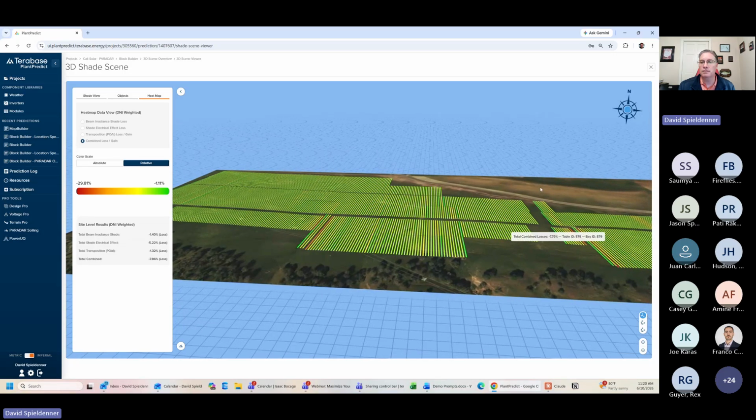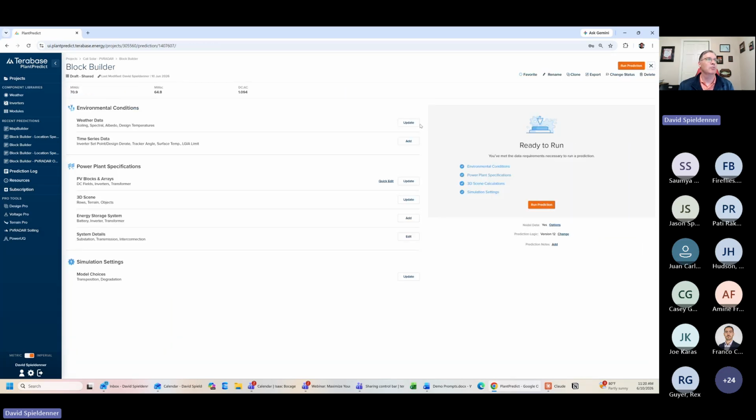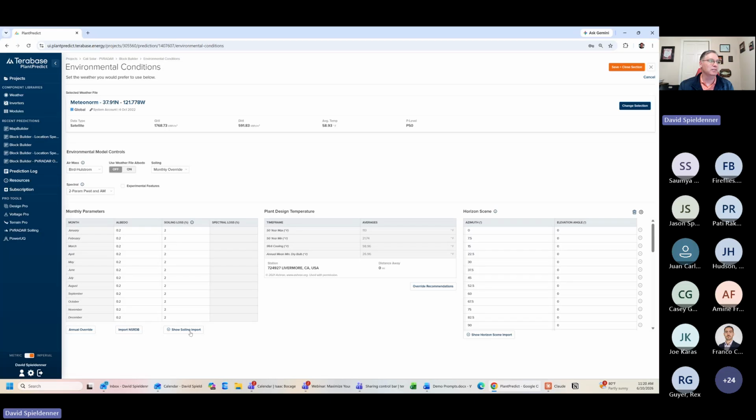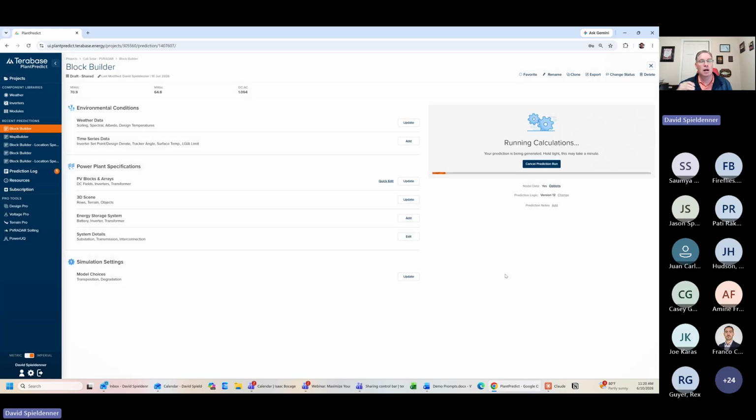However, this webinar is not about shade loss. We're talking soiling loss. So let's back out of here, and we're going to go into our weather data. You'll notice that I've modeled this with a 2% soiling loss, which aligns with 33% of the webinar participants in today's webinar. It's a pretty standard practice to do that. Now when I run my prediction in PlantPredict, it's going to take that assumed 2% loss, apply that to my prediction values, and we'll see what kind of energy results we get on this project.